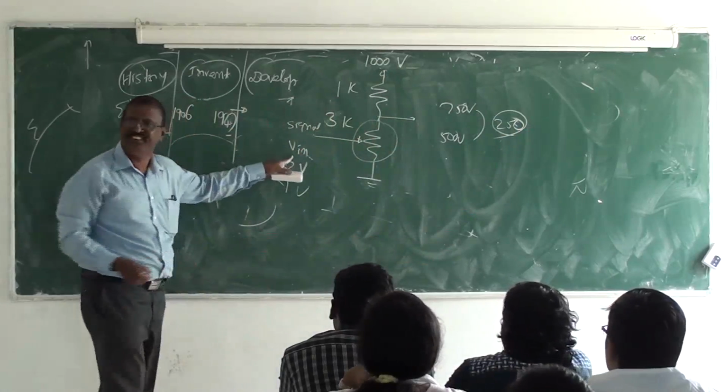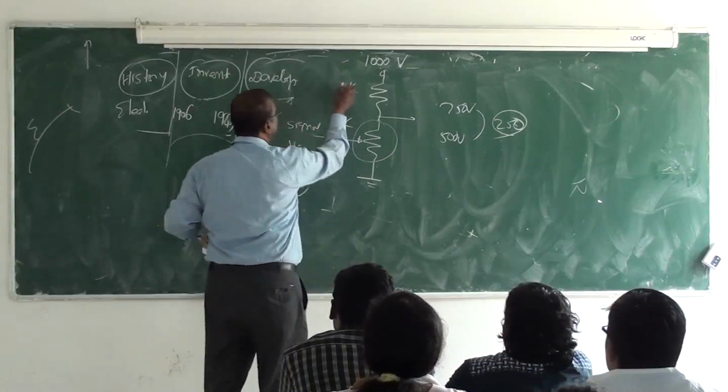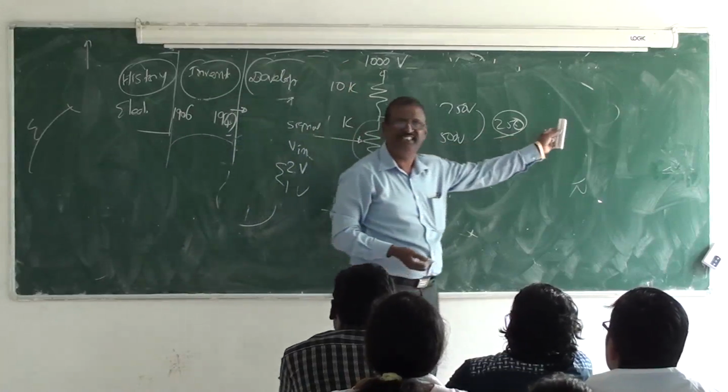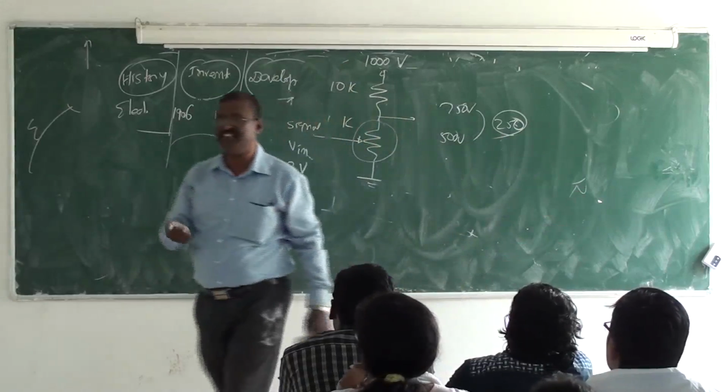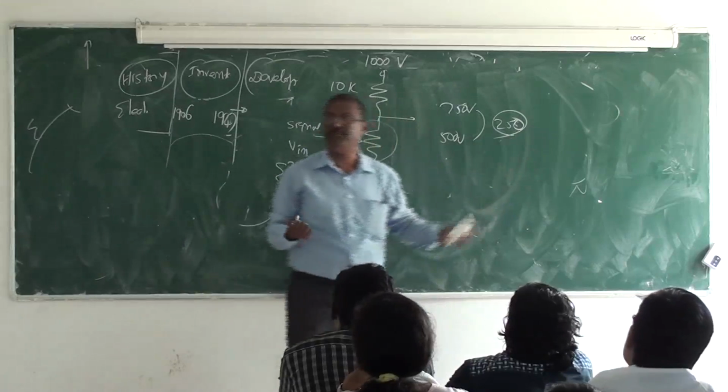I didn't change the input signal. I didn't change anything. You said this resistor is changed from less than 10K to 10K or something. Then the ratio will change, so the amplification is changed. You are actually amplifying the signal. You are not amplifying the power.